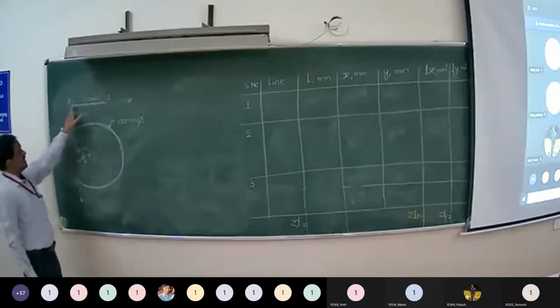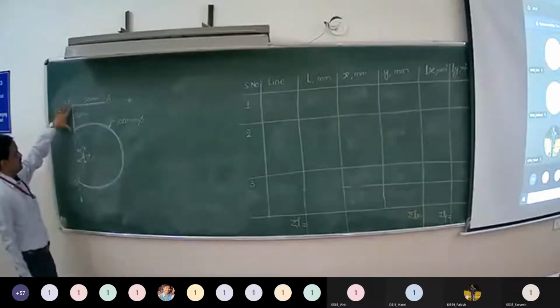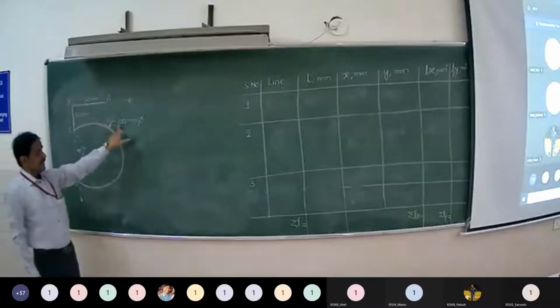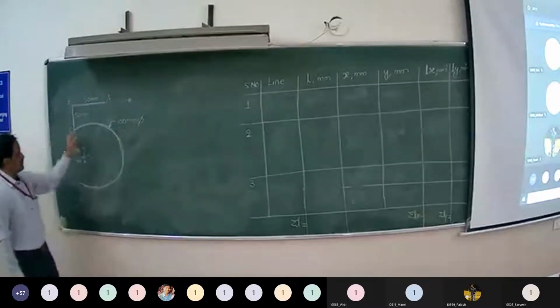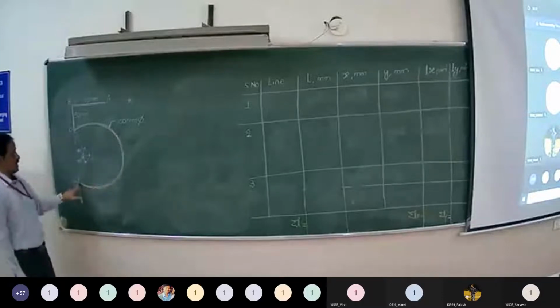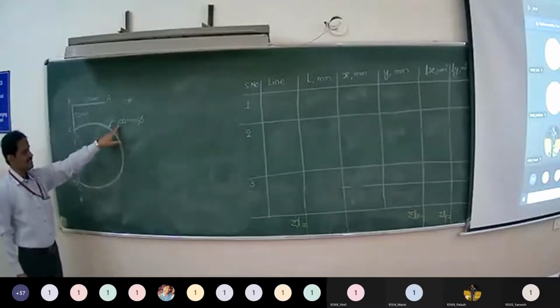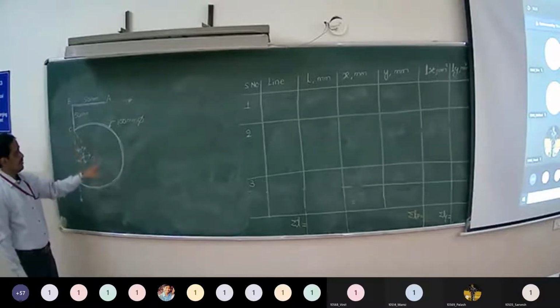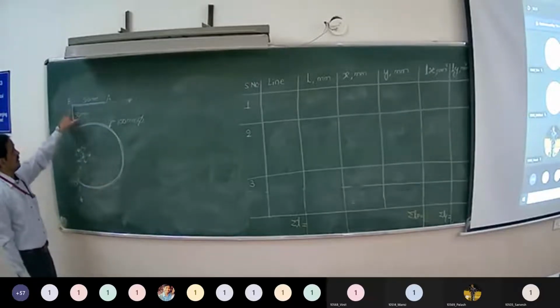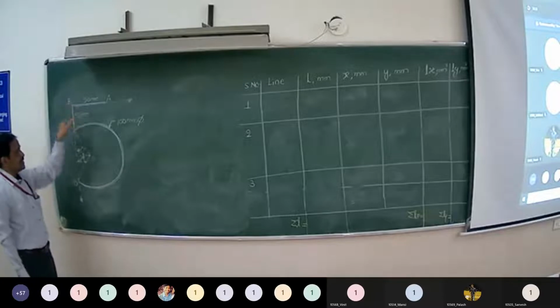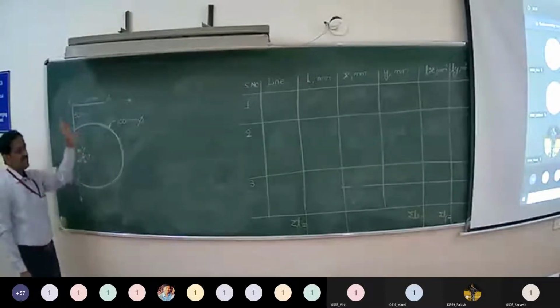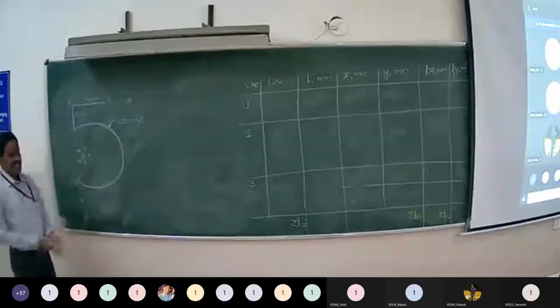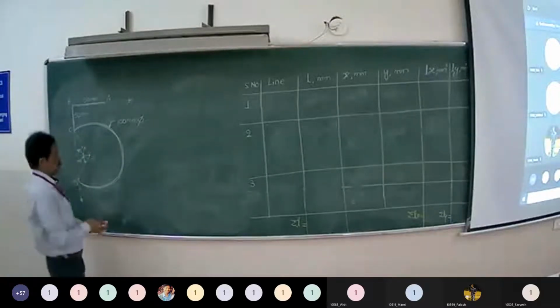So it is 50 millimeters AB, BC is 50 millimeters, diameter is 100 millimeters. So diameter of this circular arc is 100 millimeters. So you have to find out the position coordinates of center of gravity of the bend with respect to point B. B is one-dimensional body. The center of gravity coincides with the centroid of the line.